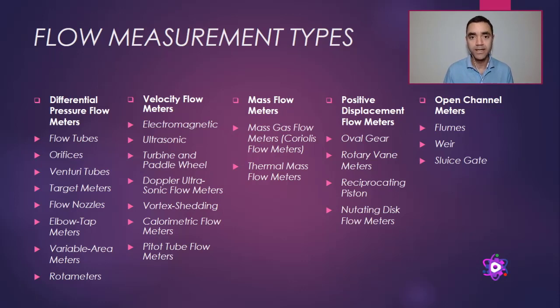We need to convert the actual volume flow that we have in the process into a standard volume flow, where we know the basis of pressure and temperature, to always have the same references for the process. That is especially important when we are talking about gases because they are compressible fluids, and a variation in pressure and temperature can vary a lot the mass density of the fluid, and that can give you totally different numbers of measurement for the same mass flow that you have in your process.